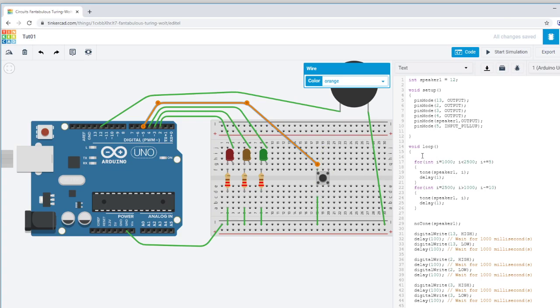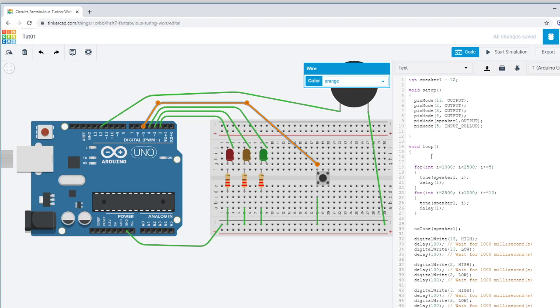But what it's also going to do is, it's always going to be on. When we press the switch, it'll break the circuit. That'll then act on it. Because of code, it makes no difference whatsoever. We can just come down and say if digitalRead, so we're reading what the state of the pin is. Digital read, good spelling.